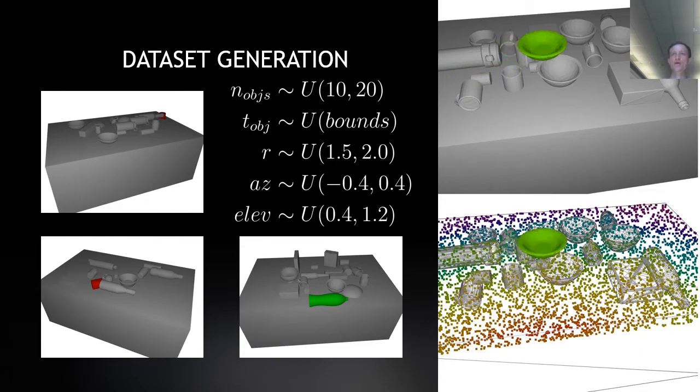To train the network, we generate a dataset of over 1 million scenes with 10 to 20 objects scattered around a table. We then choose an object that travels on 64 linear trajectories across the scene, checking ground truth collisions using FCL at each time step.